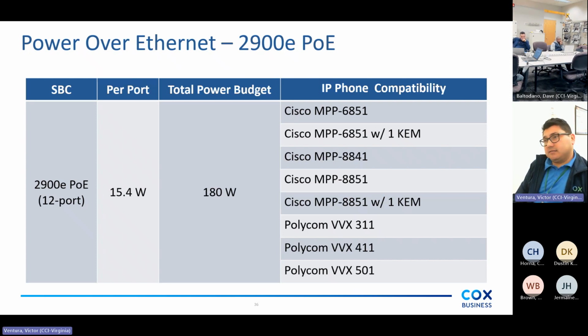As a technician, you're not going to be thinking, am I going to have enough power to power all the phones? Based on the total budget for each of the switches, with all phones, you should be able to plug in 8 phones to an 8-port switch, 24 phones to a 24-port switch, and 48 phones to a 48-port switch, and they should all get the right amount of power and be able to power all the devices that connect to those switches.